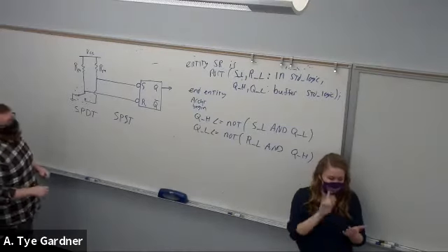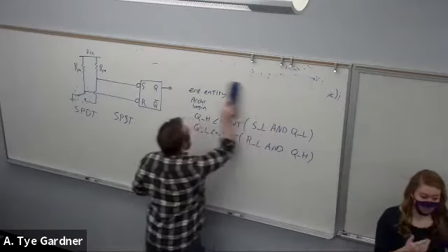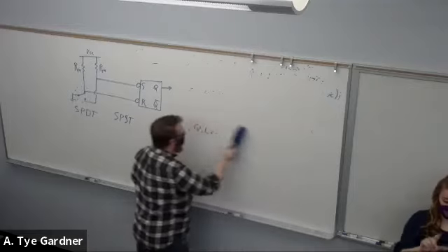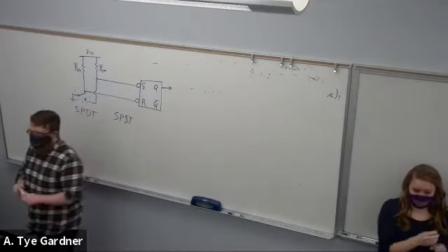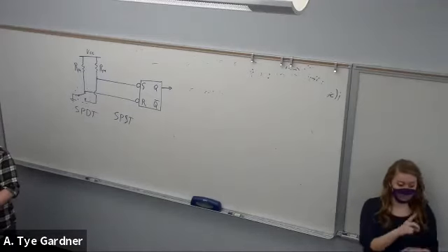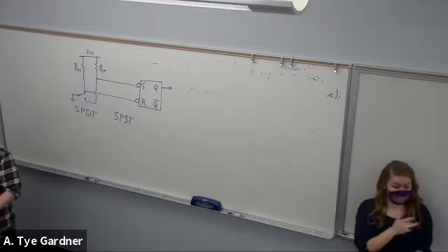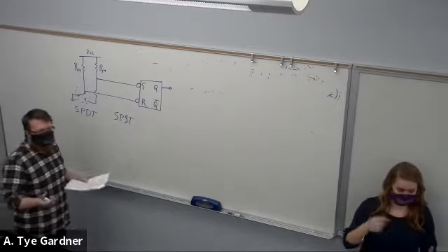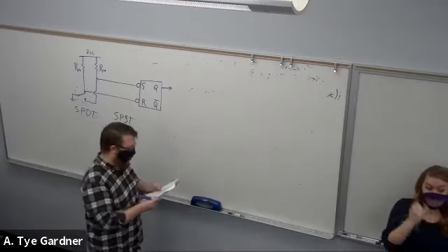Okay, the next thing that we can do with the SR latch is add just a little bit of complexity to it to make it easier to use. So what we want to build now is called the D-Latch. Now the D-Latches tend to have an enable signal on them, meaning that they're only going to respond to input if the enable is turned on.